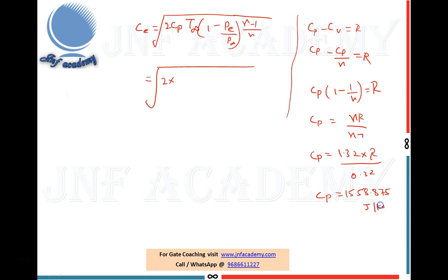Joule per kg Kelvin. Ideally the Cp of air is very easy, right? Generally the Cp of air, as we have studied, is 1005, but you should not use this value here. Because it's a hot gas, it is 1558. So there's a difference of 500 units. Keep that in mind. Don't substitute our normal air Cp, or your answers will be wrong.